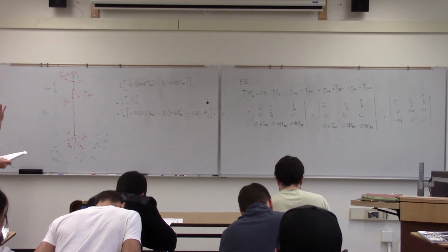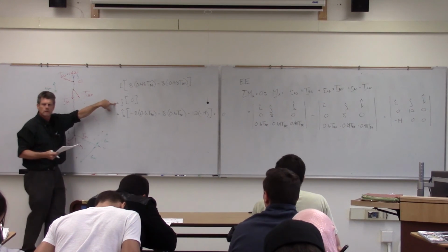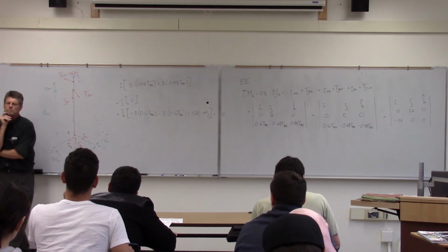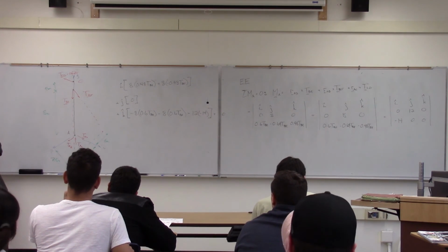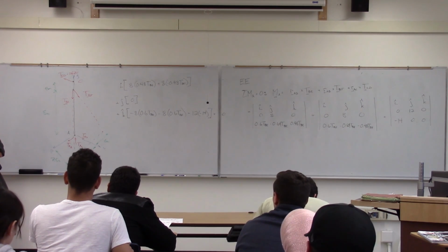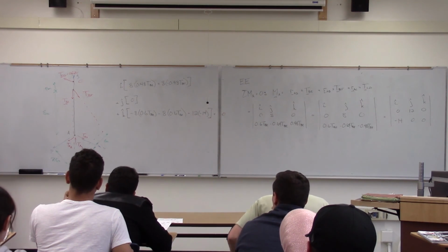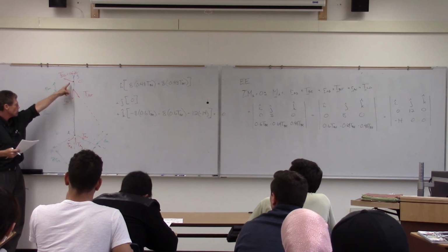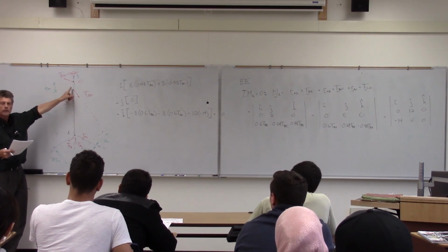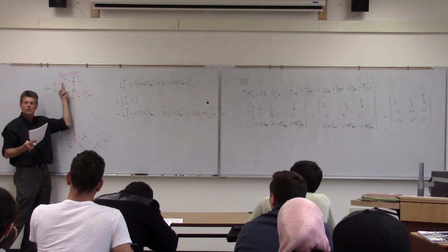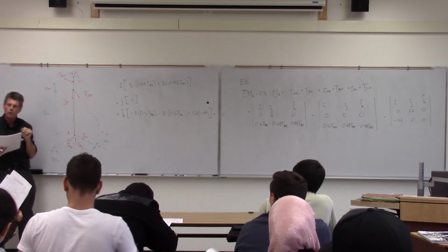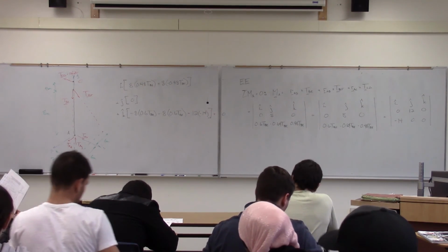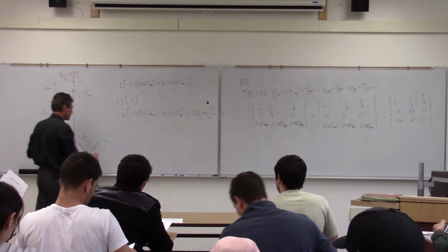Now, the reason I wanted to go this far is, does this make any sense to you? Why would there not be any sort of moment in the y direction? It's that special case of equilibrium. Remember, all the forces going to a line? All of these forces basically go to this line here. So there's no resistance. None of those forces can provide me any sort of resistance to a twist about that y-axis. So it does make sense. I'll post the solution for you tonight so you can take a look at it.